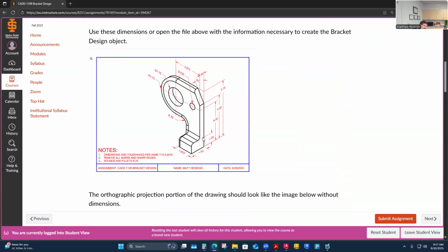And so if I lay it down on that side, yes, it'll have this little bevel up here that won't be contacting the base surface, but it's going to be a pretty stable part position. Just lay that down on that edge. And that would make this still the front surface with probably this hole being on my right side and this stuff being on the left side of my front view. So I'd almost just lay that down and look at it.